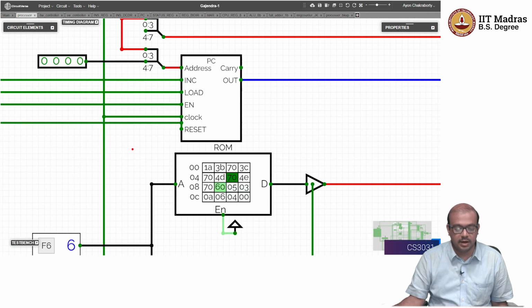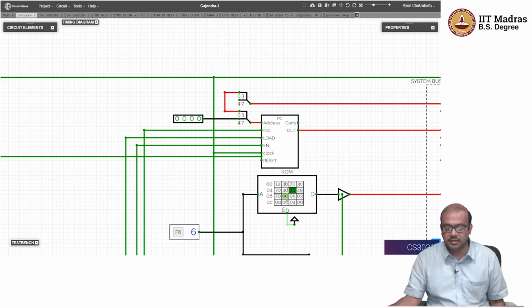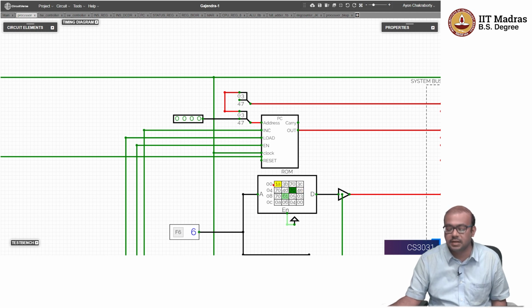Okay. Similarly, you also have load. If there is a jump instruction, for example, the PC has to be loaded by a value. So if, instead of doing 60 here, I did 61, I can try out and show you. After it reaches this point, it is not going to go to 1A, it is going to go to 3B. Instead of that, if I just simply use 61, it is not going to go to 0, 0. So 1A is not going to execute, it is going to be executing 3B. Okay, and the result might be different, because your result contains 8 at this point of time.